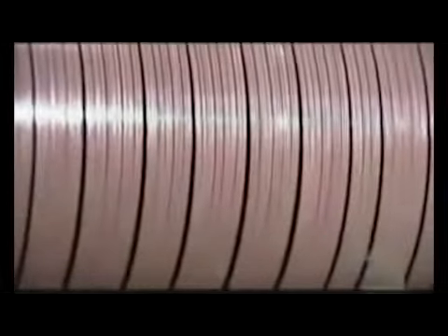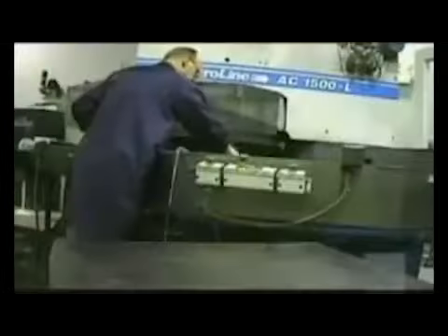Once cut, there are microscopic marks left on the wafer's surface, so it's time for a buffing using a process called lapping. After a twirl in this high-powered polisher, they are still not smooth enough. So they're given yet another buff using a chemical process. The result is wafers of silicon with a surface roughness of less than 1/millionth of a millimeter. Buffed to a sheen, they're finally ready for etching with the circuit design.